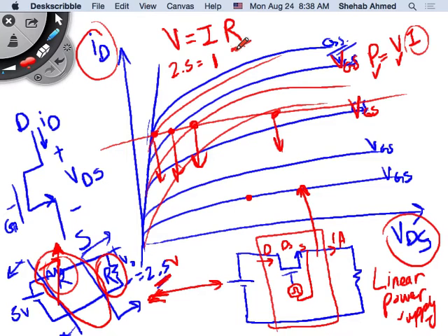But if you come to build it and you use a quarter-watt resistor, these small, tiny, flimsy resistors, it may burn. Because if I have a current of 1 amp and this resistor is 1 ohm, then I squared R is 1 watt. So if you use these flimsy quarter-watt resistors, what's going to happen to it? It will burn away, right?